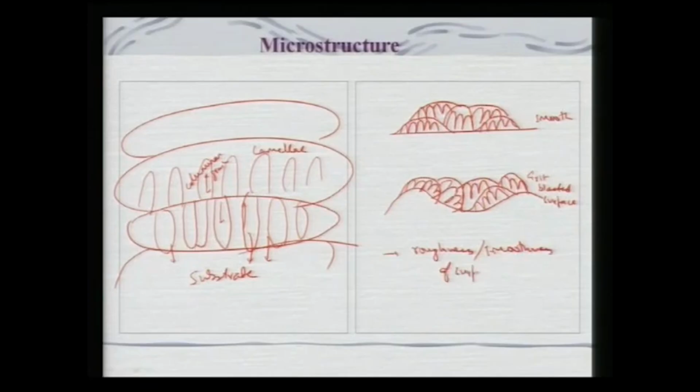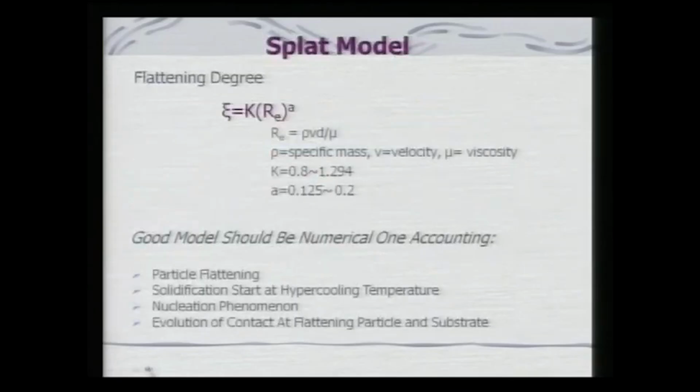surface. And as we can see, the rough surface is providing much better interlocking. So now it can provide much better interlocking along the interfaces. So the rougher the surface, the better interlocking it can provide to the deposited coating. That is the advantage of surface roughness in the development of a microstructure in thermally sprayed coatings.